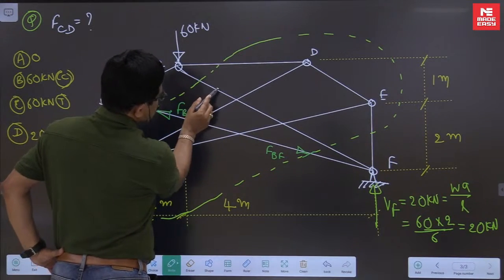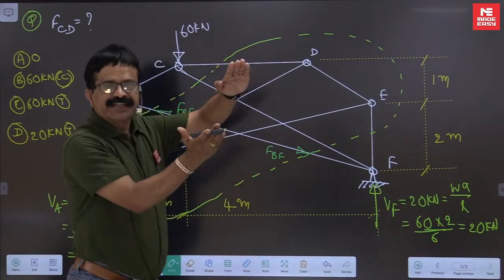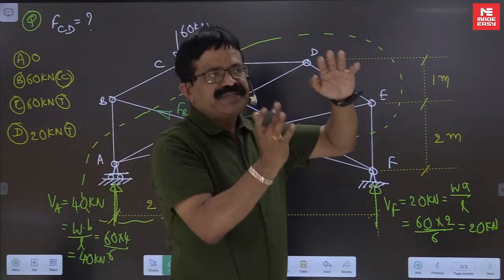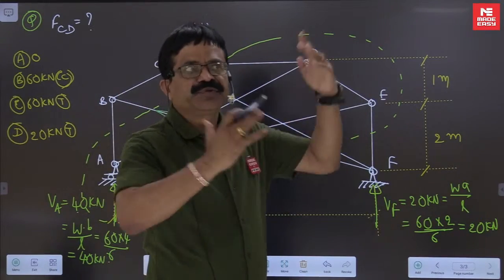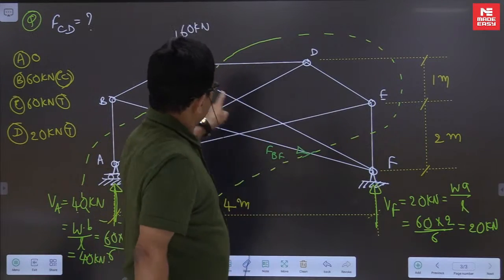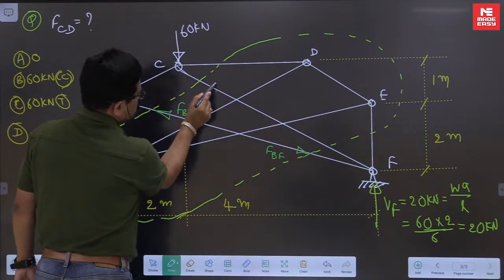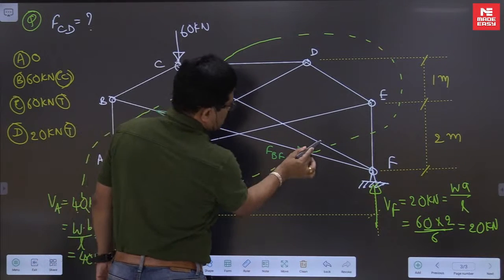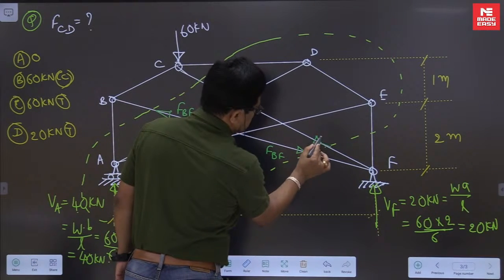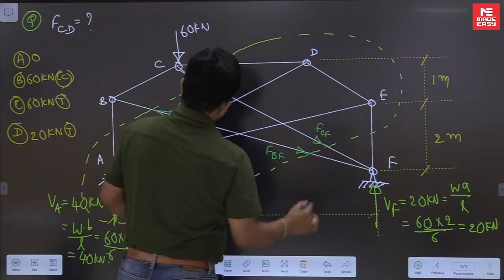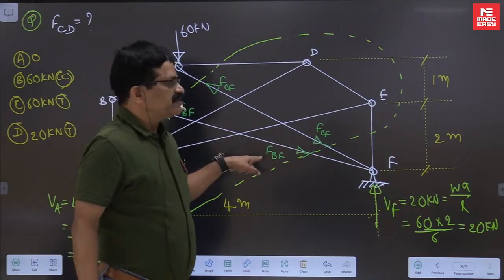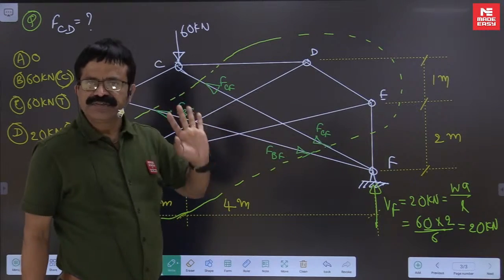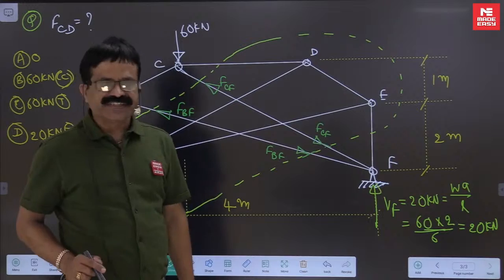What this will do on this, when I am taking this free body diagram, means it is the diagram of a body on which what others are doing you have to show. So what this is doing on this one, we don't know. So let us say force in the member CF towards the joint. Here also it is getting cut. So these two, we have cut them at two places, so they don't come into the picture in any equilibrium equation.